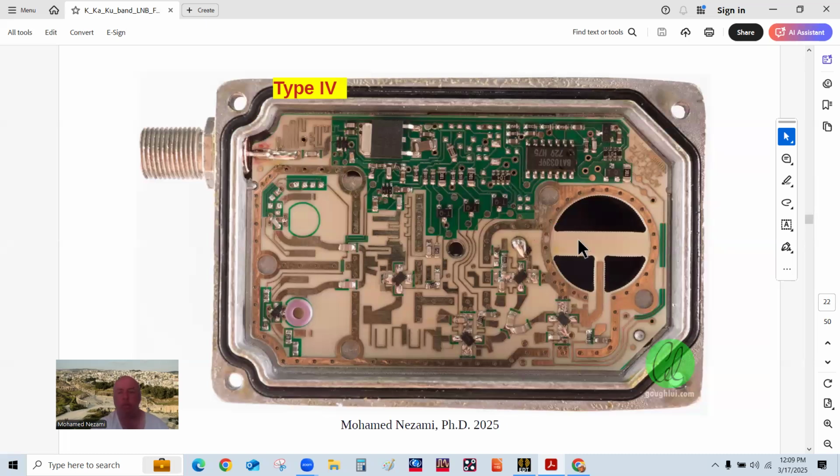Okay, so let's show here again. This is an intact LNB using the same technique. So we've got this sort of bulb in here. That's basically the pin that goes into the page and then is bent 90 degrees, and then it becomes parallel with this here, and on the other side it's metal, it's printed, it has copper artwork on it, and acts as a short back end to this pole in here.